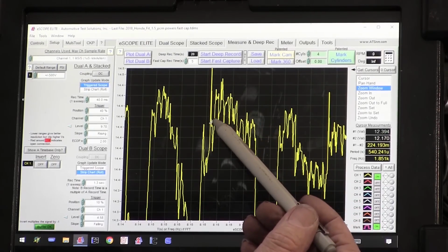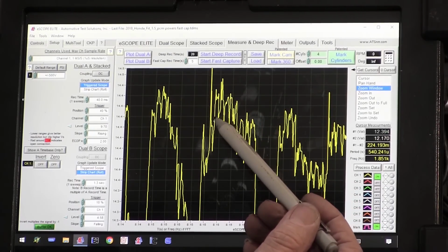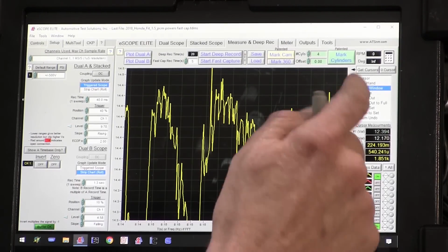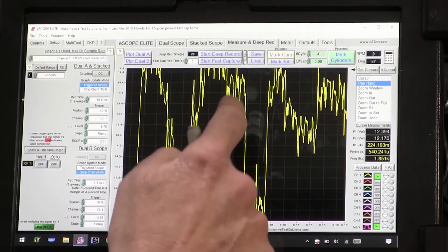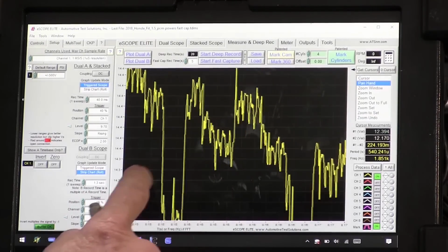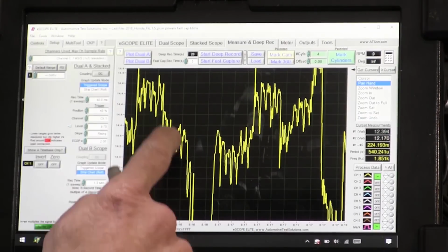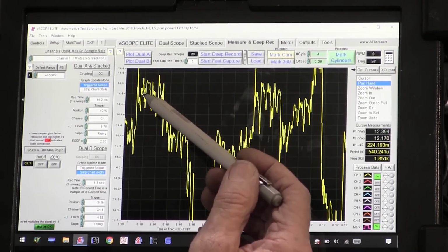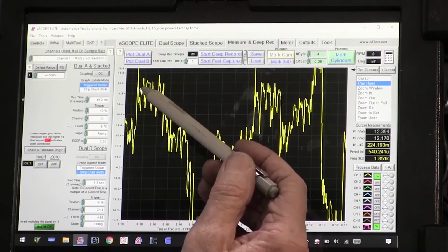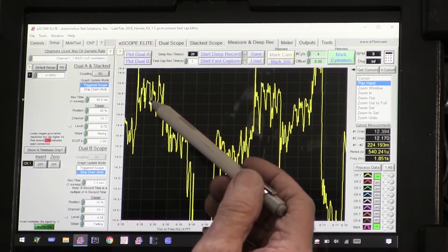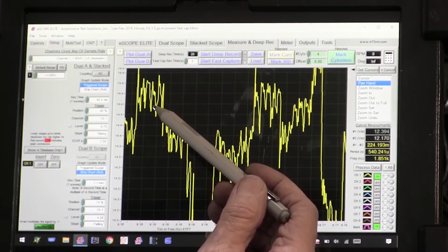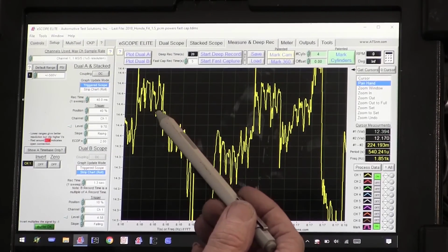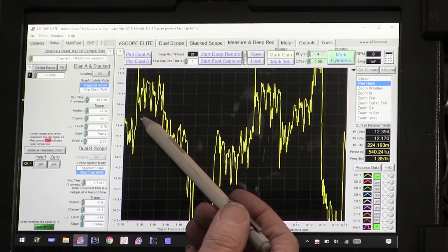What I'm usually looking for is, if I've got one diode leaking, every third one of these will have a big drop. And these drops here, this is just from things turning on that are pulling energy and I'm changing. Don't get confused on that. What I want to look at is the hump and the cut. Hump, winding output, diode clip. Winding output, clip. I'm looking for one of these to be dropping, and it will be repetitive. If it's leaking, it's going to be repetitive.